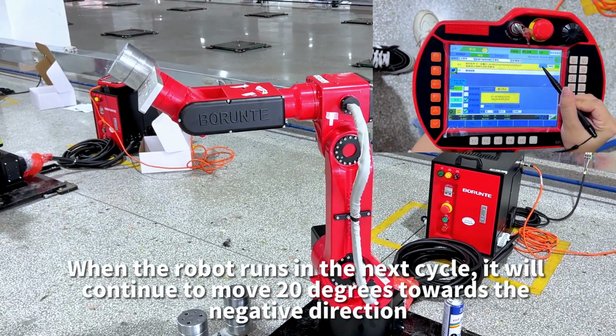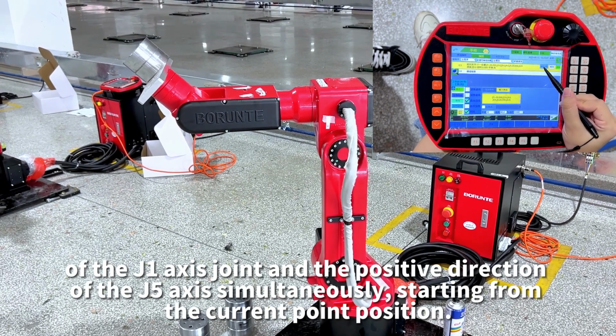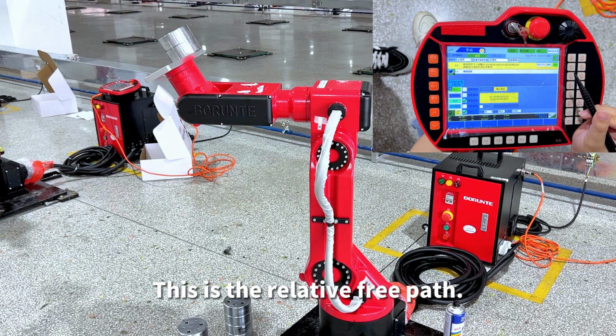When the robot runs in the next cycle, it will continue to move 20 degrees towards the negative direction of the J1 axis joint and the positive direction of the J5 axis simultaneously, starting from the current point position. This is the relative free path.